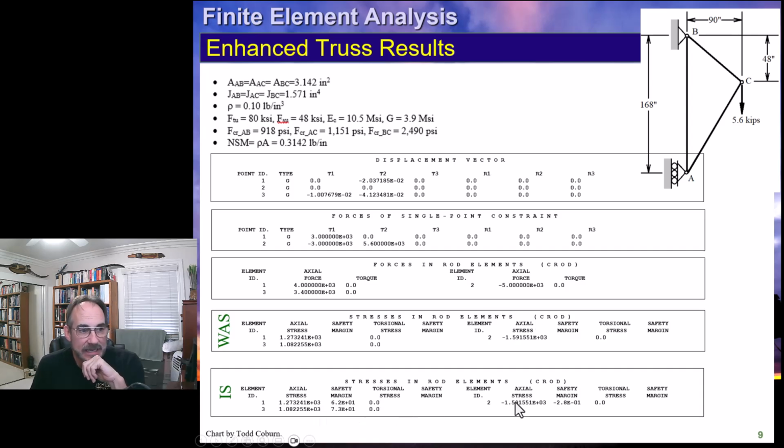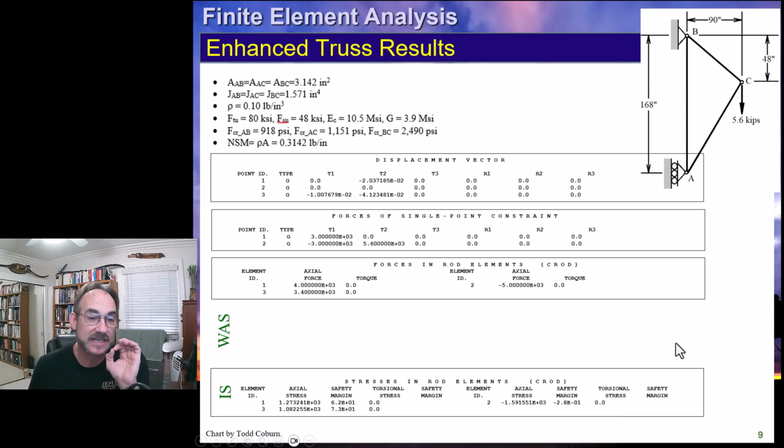That's in rod 3. In rod 2, that rod is in compression as it should be. And because it's in compression, NASTRAN writes the margin of safety relative to the compression allowable now. So it looks at rod 2's material card, and instead of putting in the compression allowable, we put the compression buckling allowable, so it writes the margin of safety against that. So that is the difference now. We now have margins of safety instead of no margin of safety, and all that was just by putting in allowables. Got that?